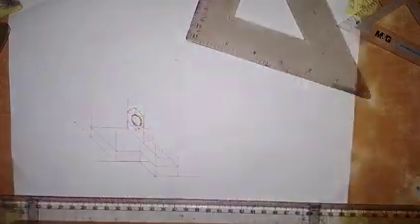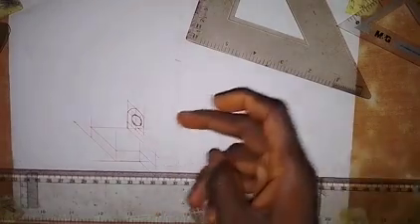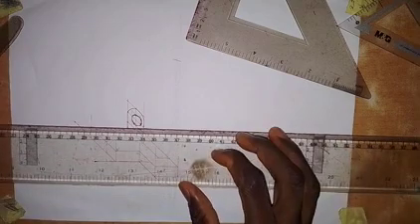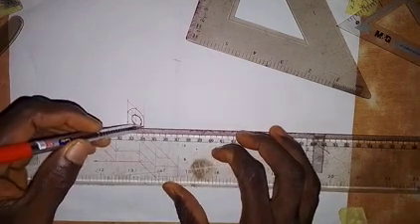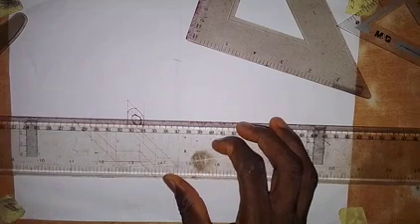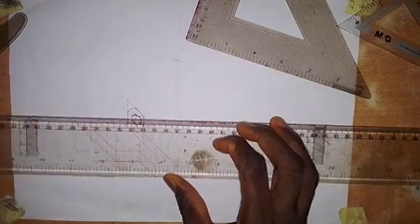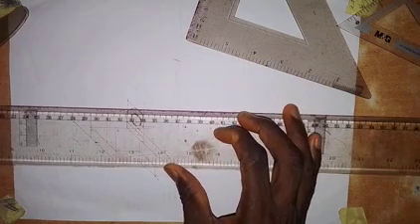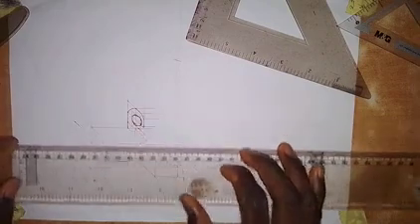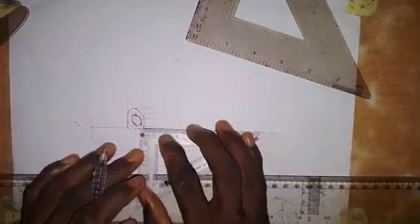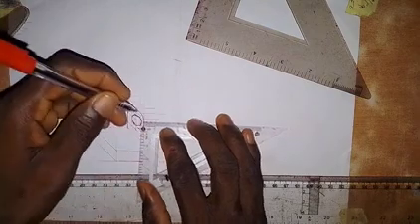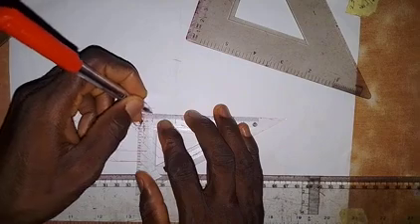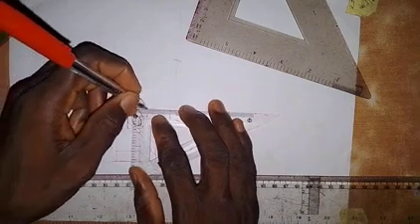Okay, and again, we also have the same curve around here. So what can we do with that? We come to this point, we draw a horizontal line to this side, and at this point also we draw a horizontal line to this side. So coming to this point, just take the point, and at this point also we draw a horizontal line to this side. So now take a measurement of 10 millimeters on each of these. So this is 10, and coming to this point, this is 10. From this point we take 10, and then from this point we take 10 millimeters.